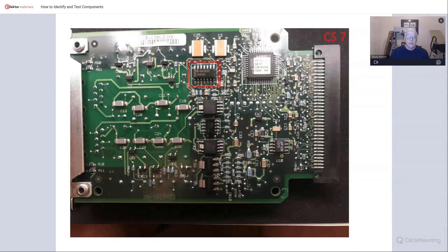This chip here foxed me for a little bit. It's got a Texas Instruments logo in the top left, and then a group of characters, 49C8T6T, which doesn't sound like a part number. Underneath that there's 2064AI. Now, the 2064 combined with the Texas Instruments logo is a pretty good giveaway. If you see a logo on a chip and you can identify it, then go to that manufacturer's website.